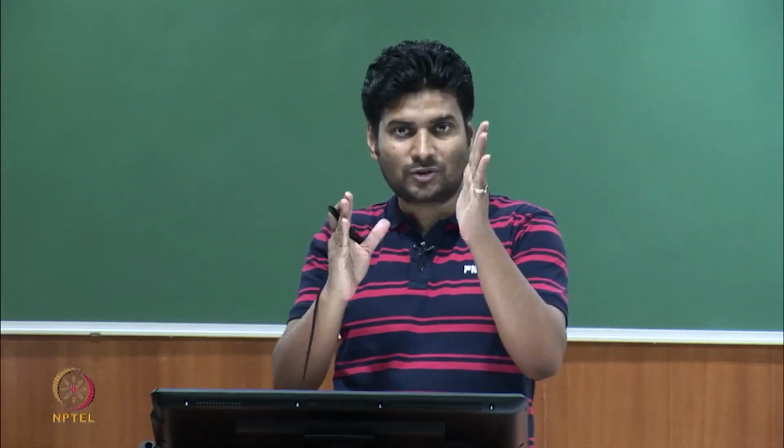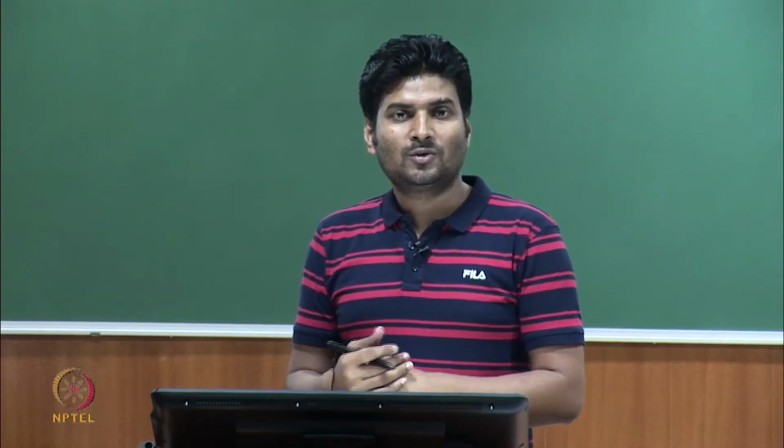Now, a beam deforms in various ways. It can undergo bending, it can undergo stretching, it can undergo shearing, it can undergo twisting. So, we have bending, torsion, stretching, shearing of beams. So, for each of these modes, we will have different forms of energy of the cross section of the beam. For example, think of simple extension of the beam.